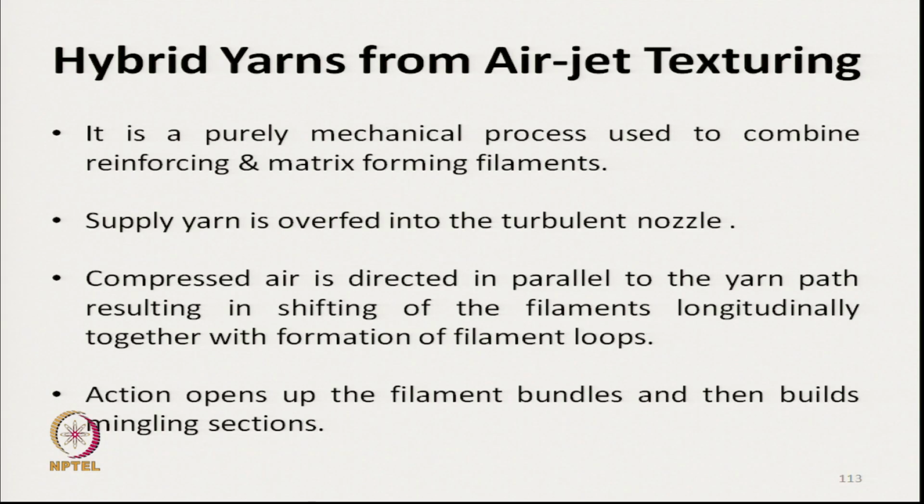Hybrid yarns are also produced from the air jet texturing technique, an almost similar process to air jet spinning, where reinforcing fiber and matrix forming filaments are combined, similar to the commingling process.